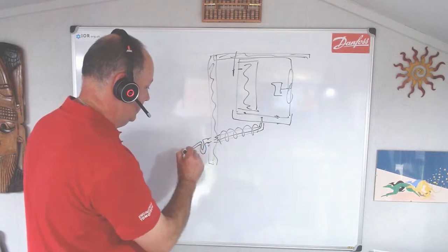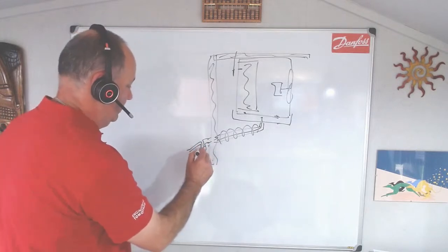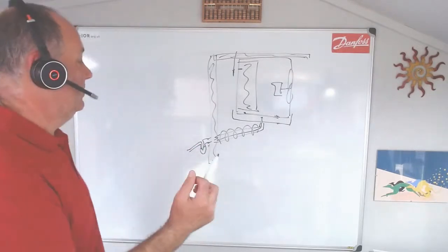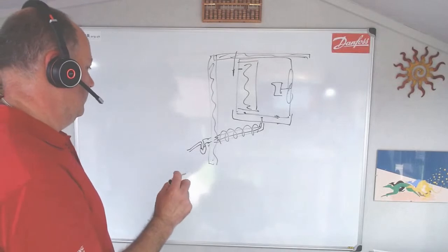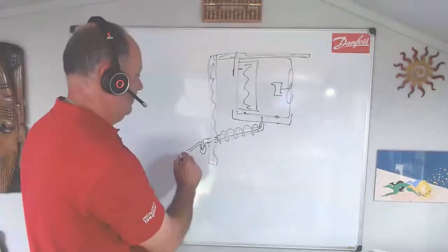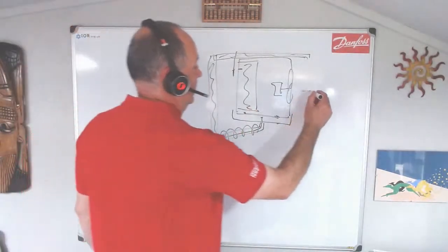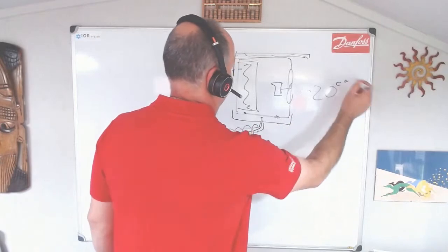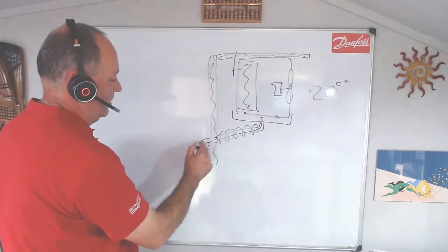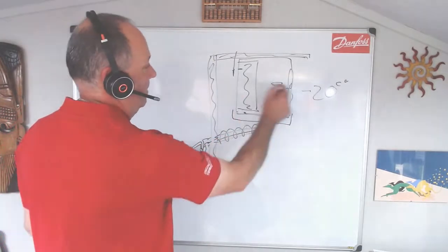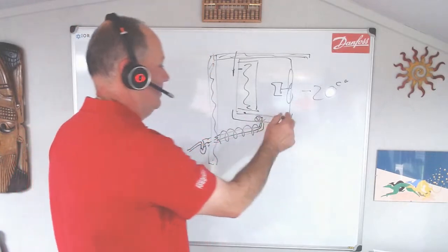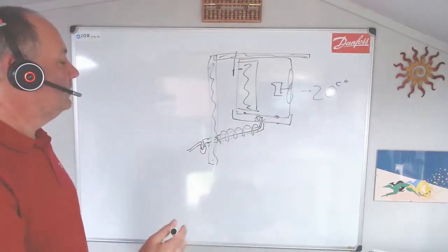The challenge becomes when your drain comes out the other side and you put a U-trap to trap your water so you don't get any smells, and also vermin, which is quite a good one from the abattoirs that I used to work in years ago. But it also acts as an airlock between outside and this refrigerated space. You've got, let's say, minus 25 there. And if that's not trapped, you get moist air coming up the drain, being pulled by the action of the evaporators, and that causes icing up issues in your evaporator because that moist air carries moisture.